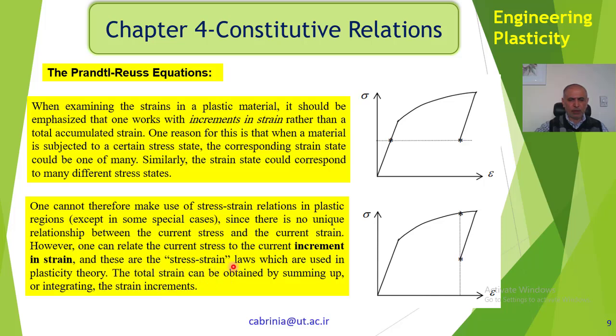Now, these are the stress-strain laws which are used in plasticity theory, based on incremental strain. The total strain can be obtained by summing up or integrating the strain increments. If we take a small increment of strain here, then we have this equation of the line. We can integrate that incremental strain between two points, for instance between here and there, or any other two points, and get the total strains between those points.